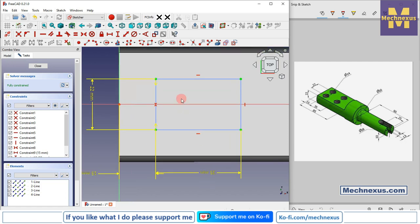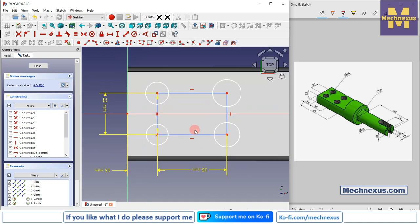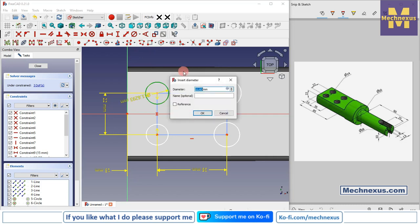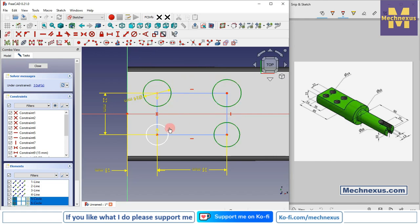So this is a construction circle, and now we will create 4 circles at 4 points of a rectangle. This construction circle is not necessary, it depends upon your modeling practice. So this is of 14 mm, so we will provide one of the circles 14 mm dimension, and I will press the control key and select all the construction circles and provide the equal constraint.